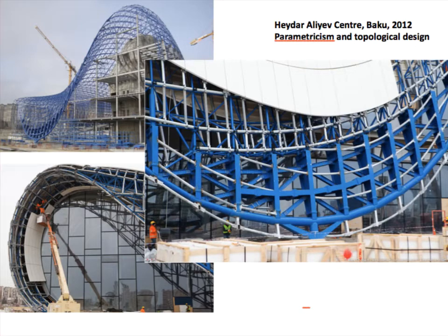Spans were variable because the roof canopy is supported intermittently on an underlying reinforced concrete armature, with maximum spans of around 30 meters. This gives an average total tube section thickness of around 60 millimeters, and gives the structure a span to thickness ratio of 500, which makes its efficiency a third that of the CNIT shell.